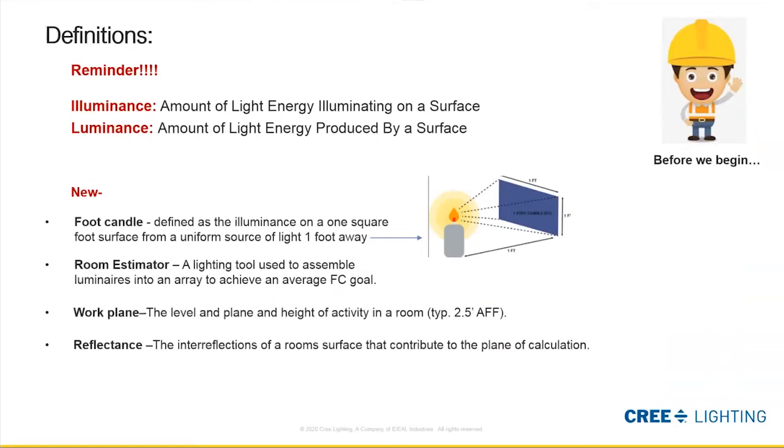The work plane. This is really the activity level in the room and also where we place our plane of calculation. This is typically shown at 2.5 feet above finished floor, which in the office environment would represent a typical desktop height. And finally, the reflectances.